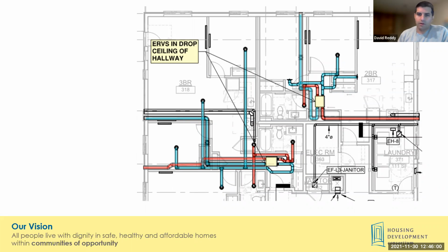There are no fire smoke dampers. All of the ductwork is contained within the dwelling unit. There are penetrations at the exterior walls, both an exhaust here co-located with the range exhaust, and an intake for the outdoor air. Distribution is to every bedroom and also the living area.